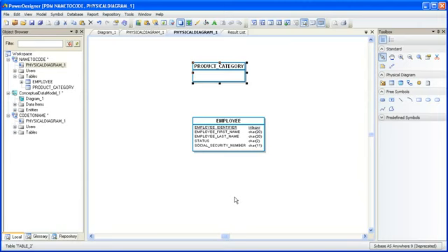To get there, you can right-click in the design area, and this will bring up a shortcut menu. Choose Model Options from the shortcut menu. Be careful not to click on an object. You must click on an open area. If you click on an object, you will not see Model Options available in the shortcut menu.